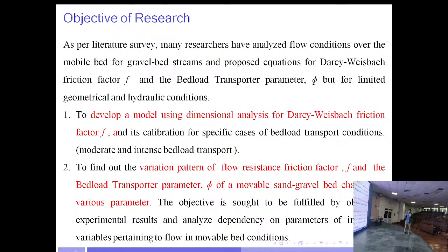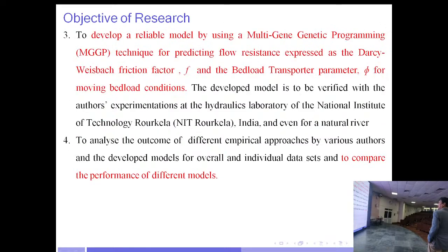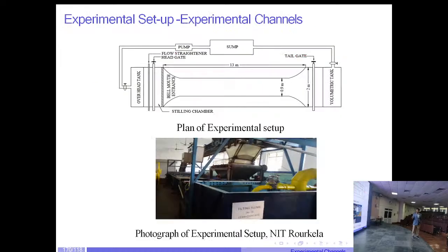Actually, his objective was the friction factor of sediment bed. How to have a good model of the friction factor of a river with bed load, and that is the friction factor. Then to have the bed load transport rate and Shields parameter, all the things actually he has developed. We have developed through his contribution.